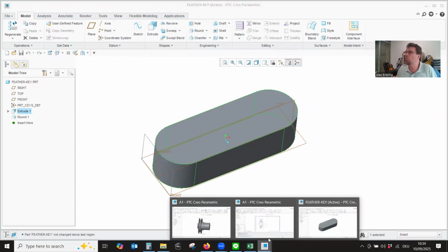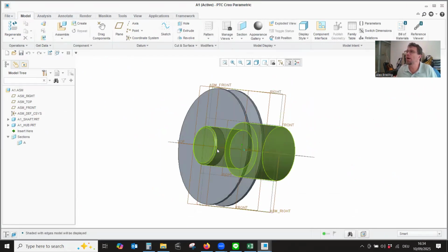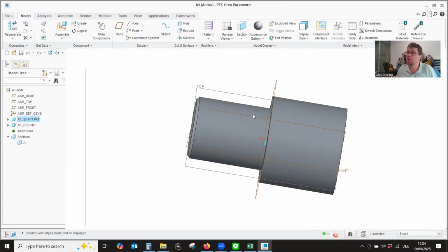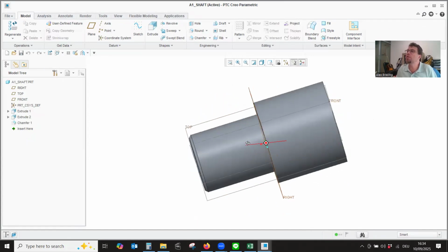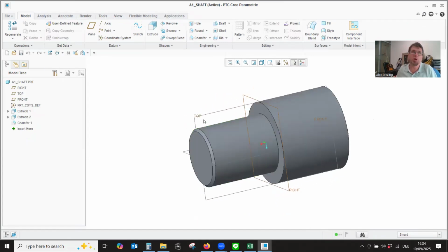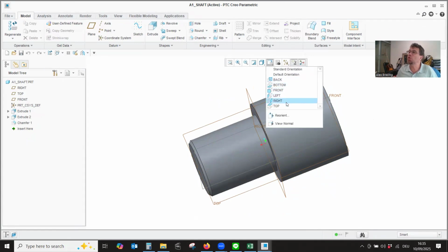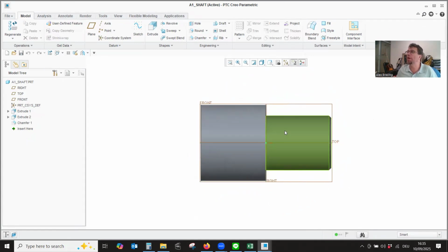So the next thing is still about modeling what I want to show. We now have to put this groove into the shaft, into this shoulder, into the smaller shoulder. And you might be wondering how to place this. Because the depth is measured from the first contact of the end mill that will cut it. But this is a round surface, right? So you can't just click on the surface. We need to create a new datum plane, and the orientation should fit the orientation of the drawing.